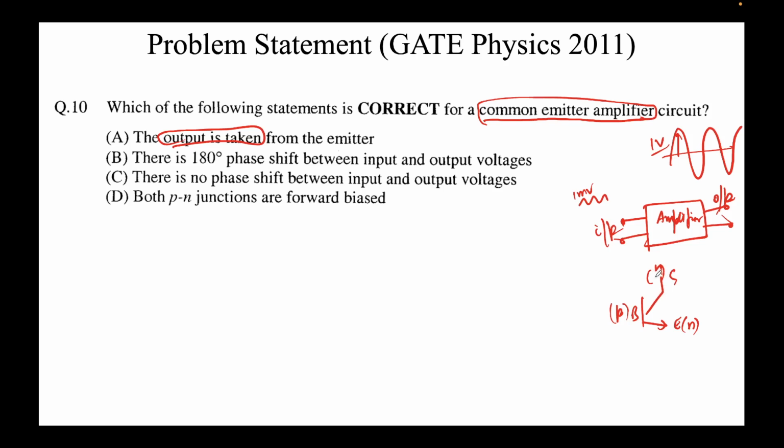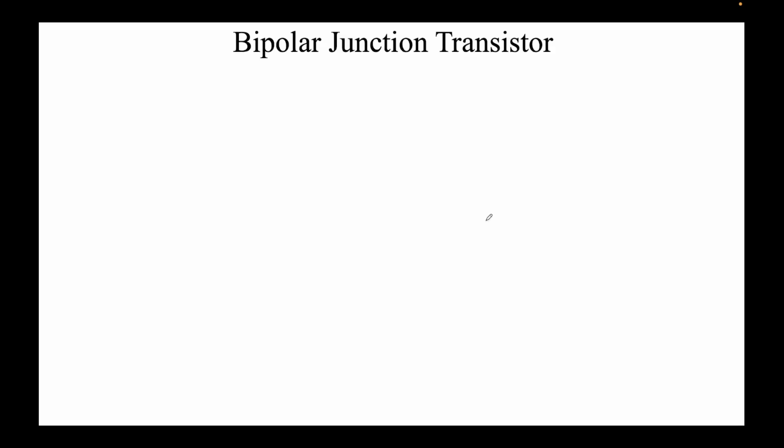Again we'll see in a bit, but for any BJT circuit, not just common emitter amplifier, at least the first and fourth points are very important. The fourth point in fact is the most important. That will determine how that specific BJT is behaving. It depends critically on the biasing of the collector-base junction and the base-emitter junction. So we'll see that in a minute.